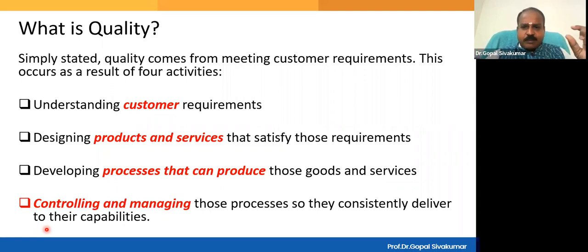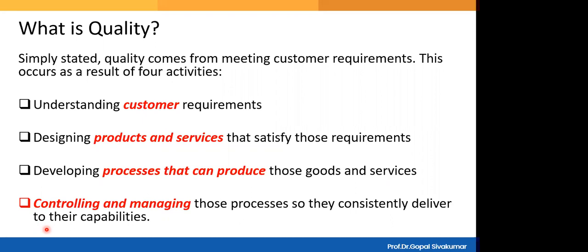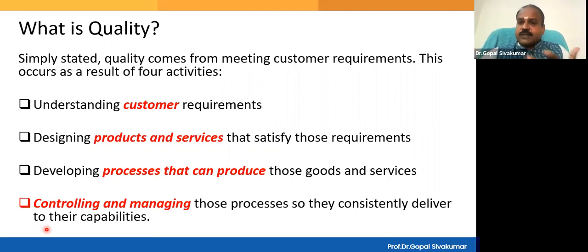And if those samples are found to be under control, you will make a conclusion that the entire shift output is under control. Am I right? You are looking at the sample, but you are judging on everything that is getting produced in that particular shift. All of you are with me? Yes, sir. This is called statistical process control.